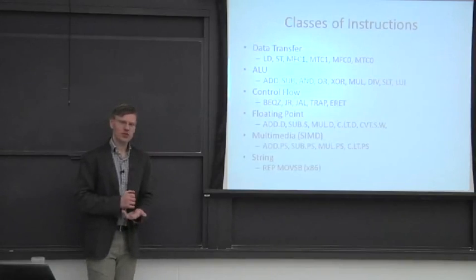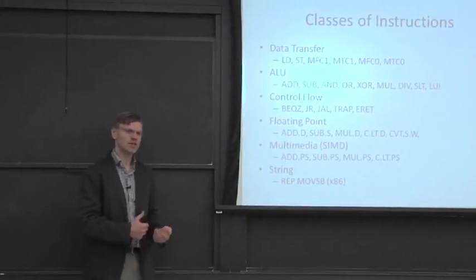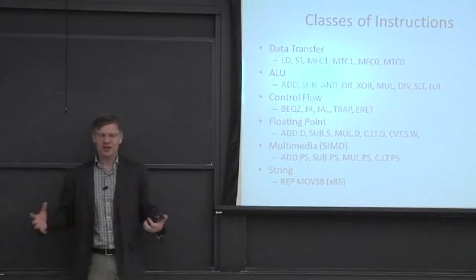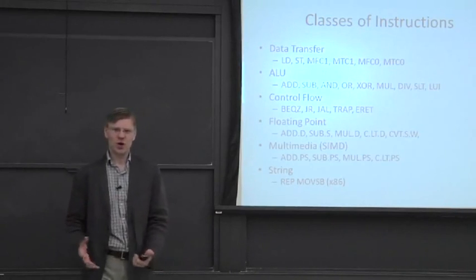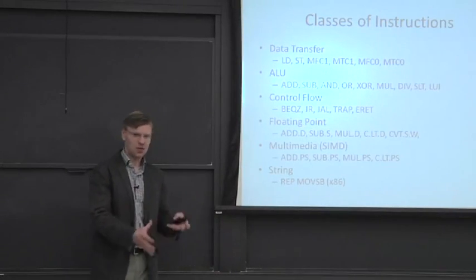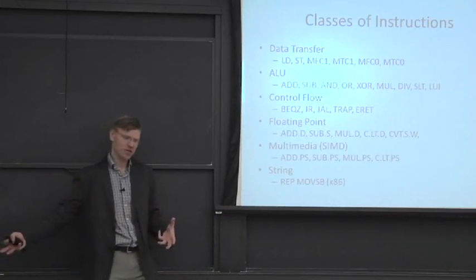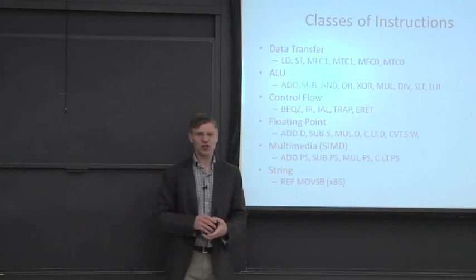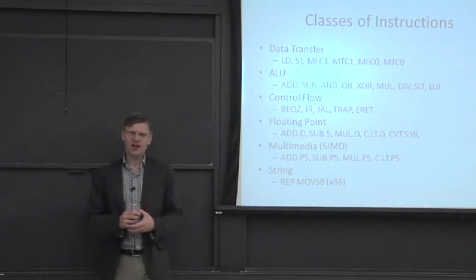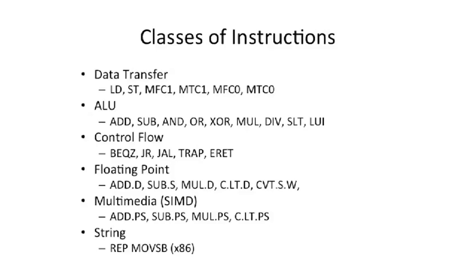OK, so now we're going to change off of machine model and talk about other aspects of instruction set architectures. And to talk about what else is in instruction set architectures, well, there's the fundamental machine model. How many registers do you have? What type of register access you have? Do you have stack-based? Do you have an accumulator? Do you have a register-register or a register-memory architecture? Also, you need to talk about what the fundamental operations are, the fundamental instructions you have.